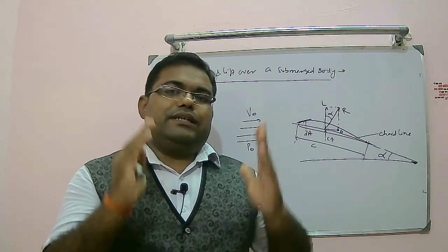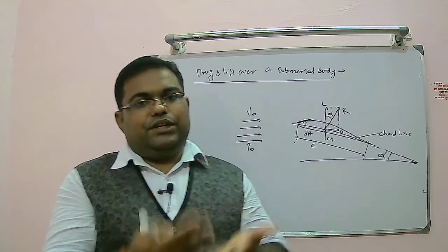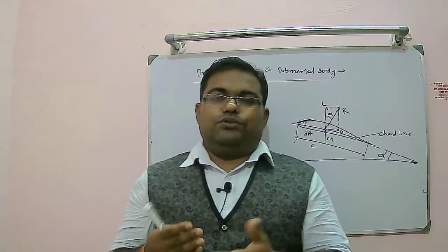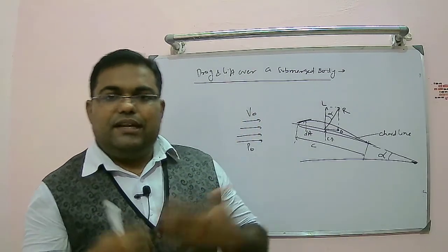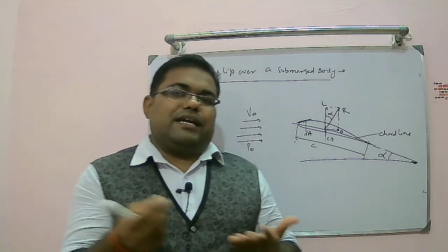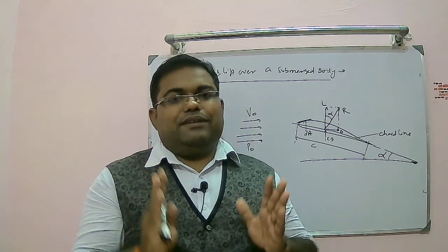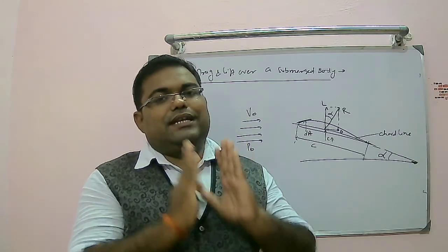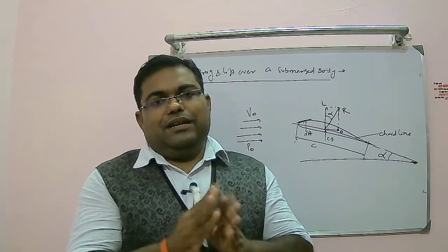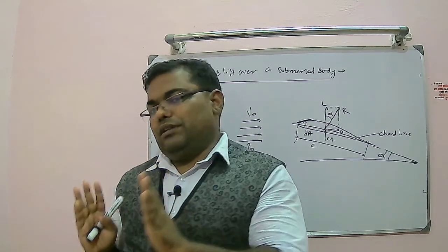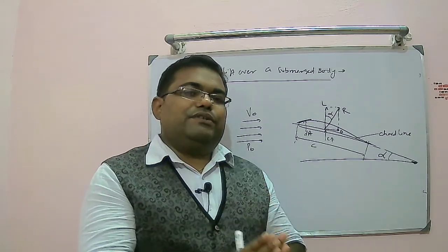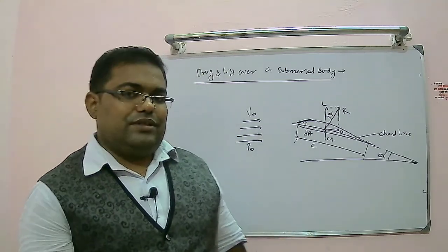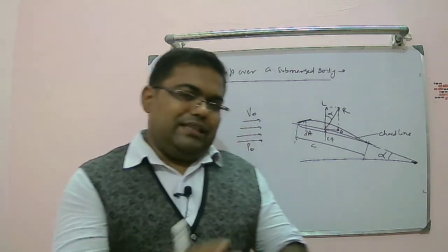Now based on the direction of the flow, basically we see what is the contribution of which kind of force. If we are talking about lift, shear force will have negligible contribution, but in drag definitely shear force will have more contribution because shear stress acts in the direction of the drag. So it will dominate particularly in the calculation of drag, but in the calculation of lift there will be negligible contribution of shear stress. Now we have to relate in what way these are related.